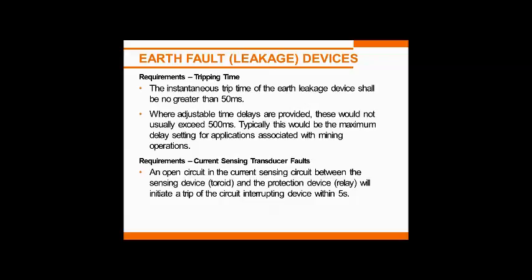Also, the standard has a requirement to make sure that the transducer is in circuit. And so basically we have to check that the toroid is connected to the relay, and that can be done two ways. You can either have a loop going out into the relay with a small current or frequency current that you can check to see if it's there, or in the case of the ELV, LD, we put out a high frequency signal out to the toroid and make sure that there's an inductor connected to the actual relay itself, so we can check that it's within circuit.